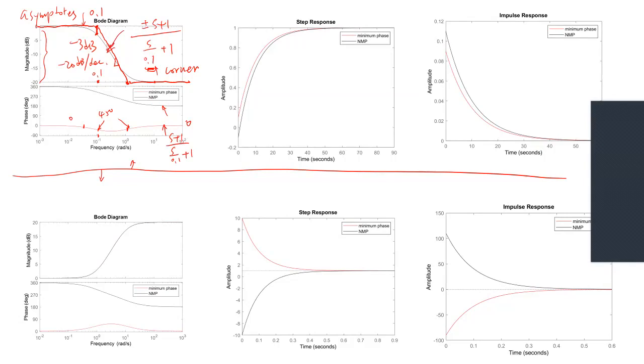Okay. This one is the same, which is s divided by 0.1 plus 1, s divided by 1 plus 1. So this is a plus or minus. You can see the phase is leading, it's bigger than 0. So this is lead then lag. The same thing here, you have 0.1, you have 1.